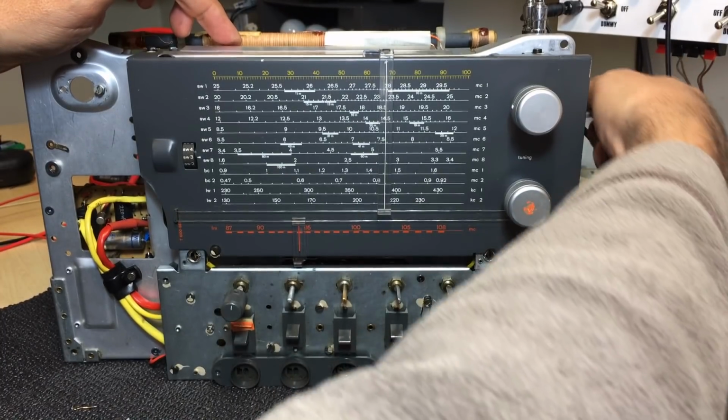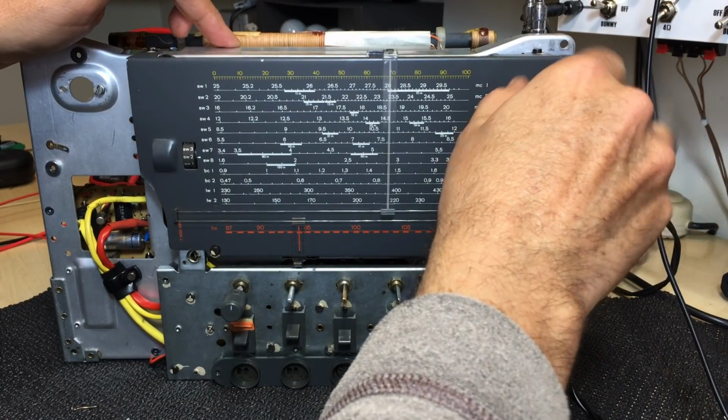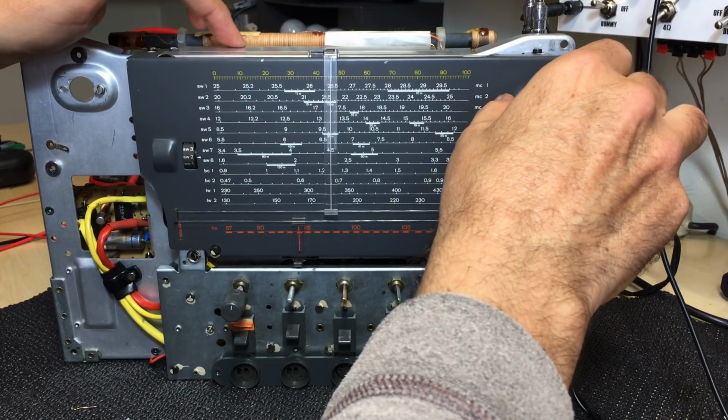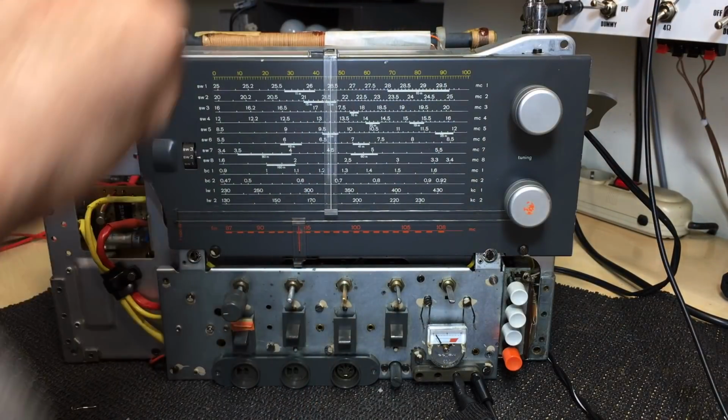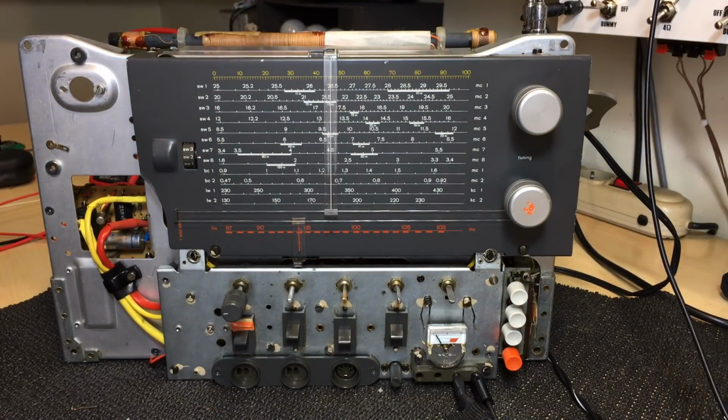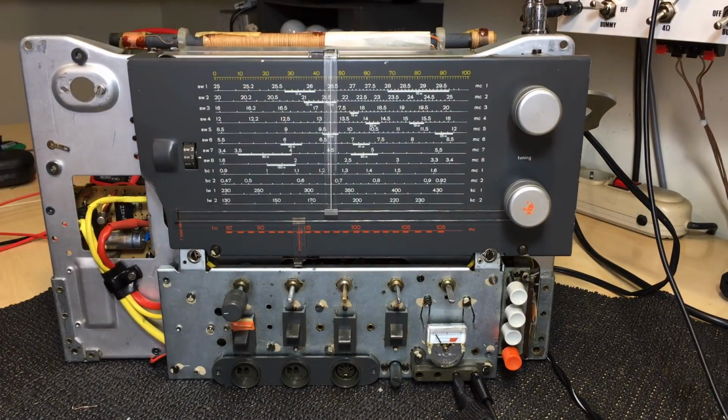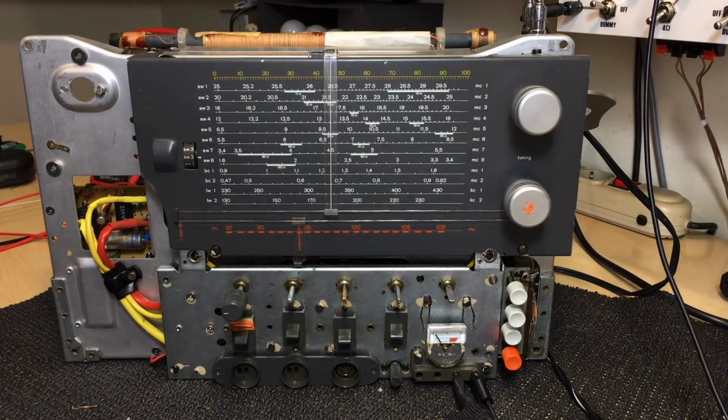And if I go down, now it's on all of them. Earlier it was just on a couple of those bands, now it's on all of them. So there's still something, not shorted, there's still a problem with the contacts on those barrel connectors. And it's not a cleaning issue, it's actually the bending motion, the pressure that those things are making in there. And I really am afraid to mess with that. If anybody's got any good suggestions as to how to tighten them without risking breaking them, I'd really appreciate it in the comments.